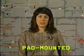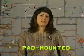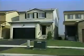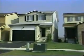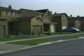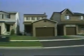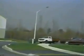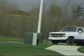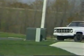For underground residential distribution, the pad-mounted transformer is generally more popular than the subsurface type. We see here a pad-mounted transformer in a residential development. The primary feeder and secondary circuits run underground, but the transformer is mounted at surface level, so improving accessibility. The external cabinet is relatively unobtrusive, and simple landscaping is often added to improve the appearance.